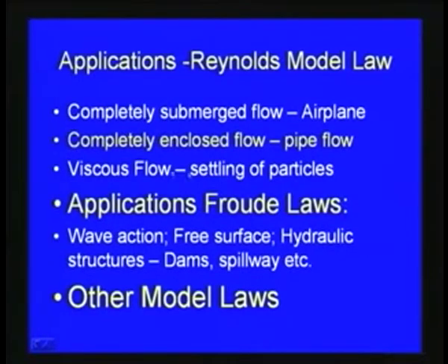And then the second one is completely enclosed flow. For enclosed flow like pipe flow, Reynolds number is more important, so we will be using the Reynolds model law. And then the third case is viscous flow like settling of particles, like reservoir sedimentation or dust settling. In all these cases the Reynolds model law will be important, and we can utilize the Reynolds model law for these cases.